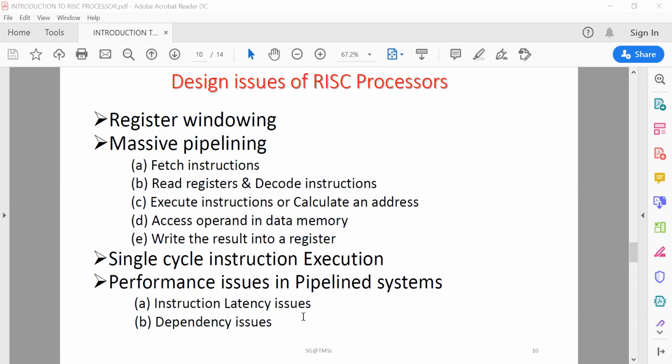A poorly designed instruction set can cause a pipeline processor to stall frequently. Some of the more typical CISC instructions which have more instruction latency should be avoided, and these are the highly encoded instructions, such as those used on x86 machines, which need complex decoders. This should be avoided. Another is the variable length instruction, which requires multiple references to memory to fetch the entire instruction, and should not be considered for inclusion.